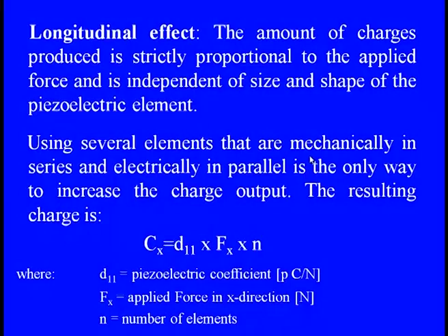And if we are not going with this, and we go with the longitudinal effect, then the amount of charge produced, Cx, is strictly proportional to the applied force and absolutely independent of the size and shape of the piezoelectric element, because the force now acts along this direction. We know that when we focus on the neutral axis, the layers of the fibers are well settled. So the piezoelectric coefficients and the neutral axis line and charges line are to be considered separately, and since it is independent in the longitudinal effect, the charges generated do not depend on the size and shape of the piezoelectric element.